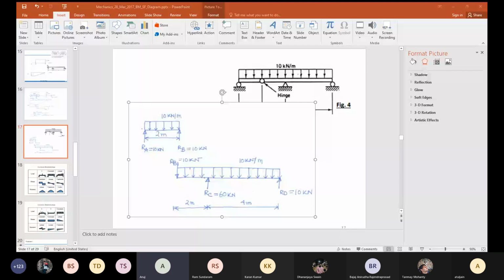Sir, we will take the same reference for both the parts. If you take the same, be careful while drawing the bending moment diagram of the second one. Then all your equations will be in terms of x minus 2. My advice is to take two separate ones, just draw the two bending moment and shear force diagrams, imagining that the other one does not exist.